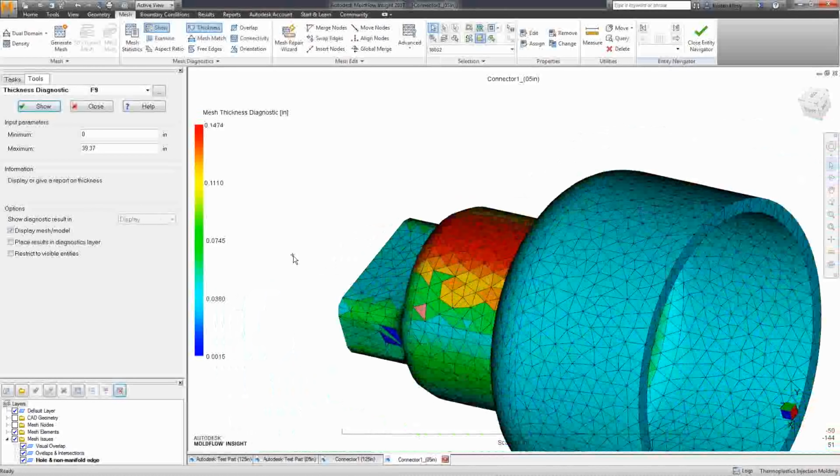Thank you. Another question we have is: is there a recommended maximum average aspect ratio for 3D tetra elements for models to be used in a warpage analysis? So for example, below 5 or below 4. We also had one of our support specialists answer this question, but I wanted to see if there was anything you wanted to add to it, Kristen. Basically, there is no specific guideline. However, if you follow the guidelines for surface to thickness, so surface edge length should be 2 times the thickness, then you should be good to go.